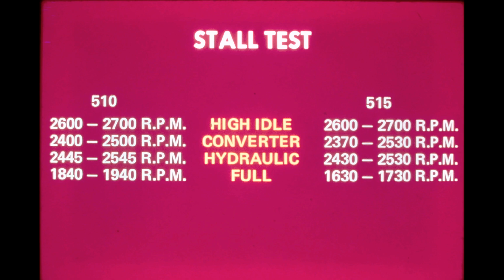If the high idle RPM and the hydraulic stall check RPM readings are within specifications, and the converter and full stall check RPM readings are high, malfunction of the torque converter transmission charging pump might be suspected. Another possibility would be leakage in the converter, transmission, or control valve.